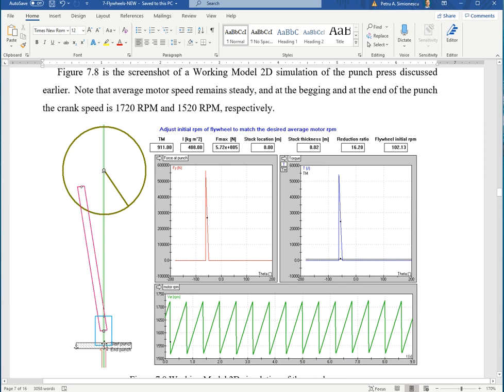I have some reference points, and I have a reference point on the punch, and I'm using the formula language to determine if the reference point on the punch is between the beginning of the punch point and the end of the punch point. If so, I'm using this F max to generate the resisting force.